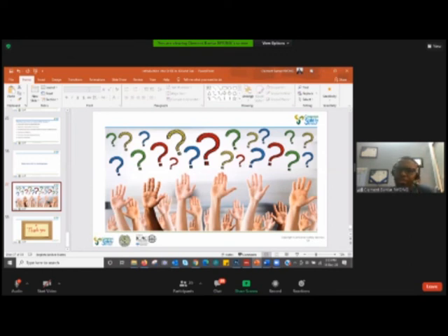You know, hydrogen sulfide is heavier, denser, so it settles in lower places. So what will be done is to put people at the uppermost part of the rig, usually the heli deck for offshore. People will move to the heli deck, and they will also be advised not to follow the direction of the wind.